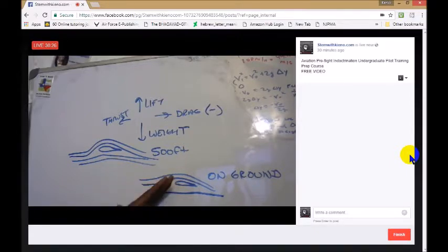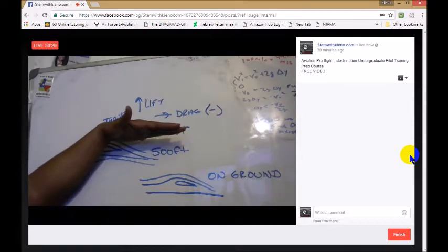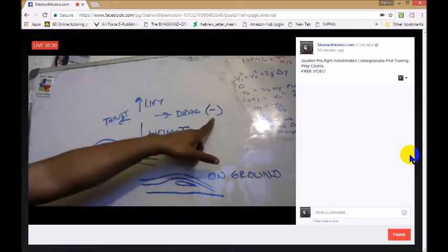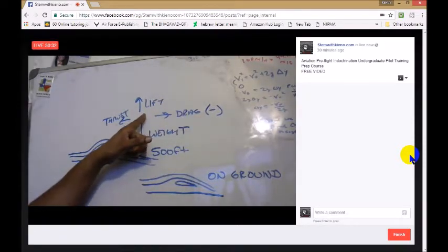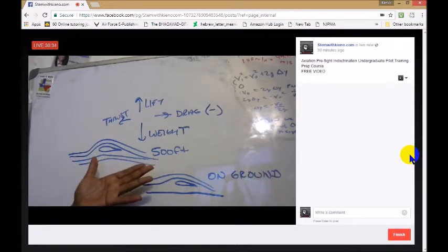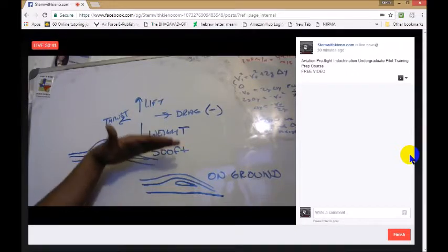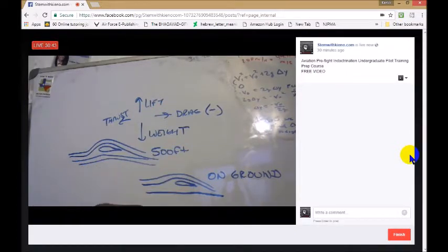Because if we climb out above one wingspan, then this drag comes back with the same amount of lift, and we're at a slower airspeed, and that's not going to be sufficient to keep the plane in the air. So we could have an abrupt settling back down to the runway if we're not careful. Now, pilots are trained, so all you passengers or people looking at this video, oh my God, ground effect, do not freak out.